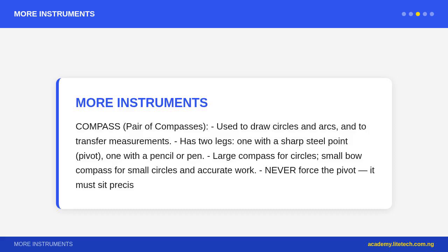Pencils. Graded by hardness: 9H, hardest, lightest line, to 9B, softest, darkest line. Technical drawing uses: H or 2H for construction lines, thin, light, HB or H for object lines, medium, B for visible outlines. Always use sharp pencils. Blunt pencils create wide, inaccurate lines. Eraser and erasing shield. Erasing shield has small holes, protects nearby lines while erasing specific ones.